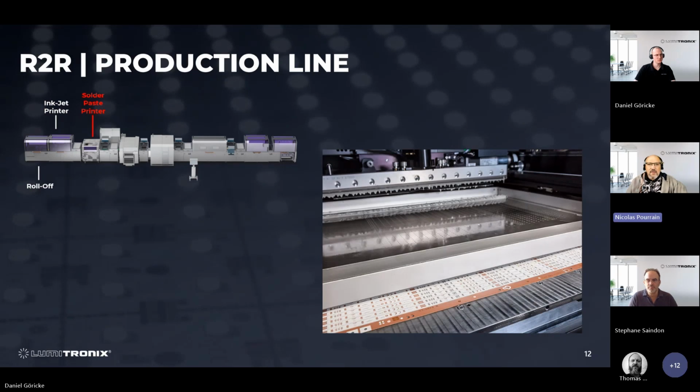And after that, we have the solder paste. This is a fully automated solder paste printing system, and the width of the solder paste can be up to 610 millimeters. This is going to optimize cycle time by a few seconds, because if we are running 610 at the same time, you are going to optimize your cycle time in production.